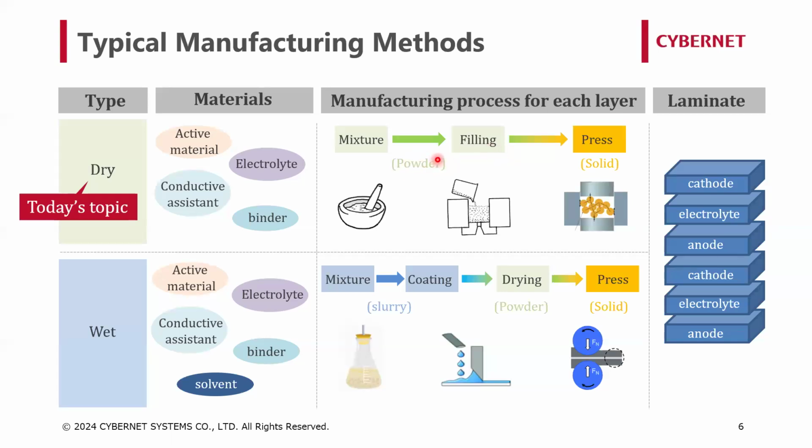Powder has such unique behavior that it is considered a fourth phase, different from fluids, liquids, or solids. So it is important to apply powder-specific techniques when handling them in simulations. The compaction process also will behave like a powder immediately after startup, but as densification progresses to a certain degree, the behavior changes to almost solid.